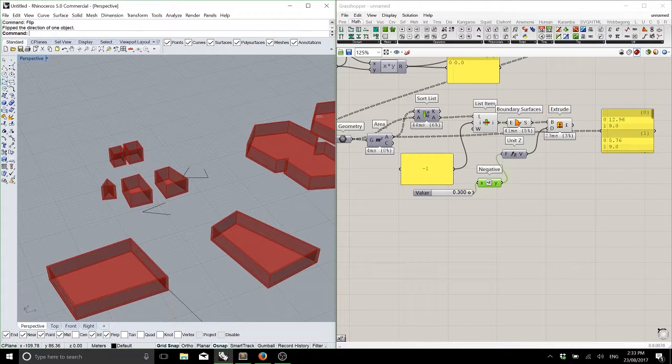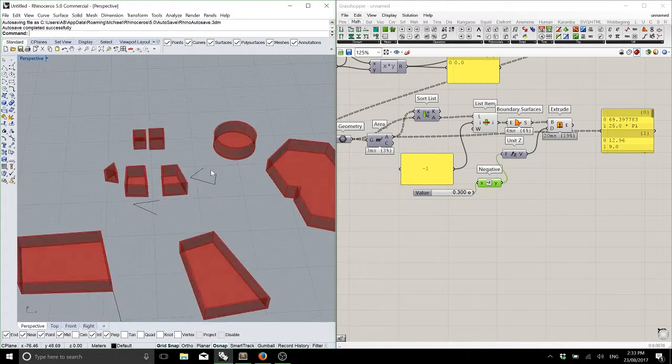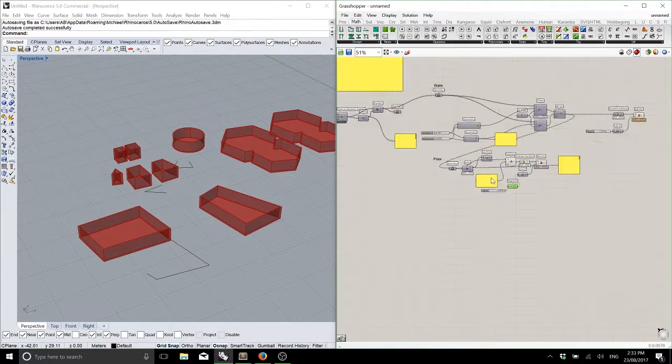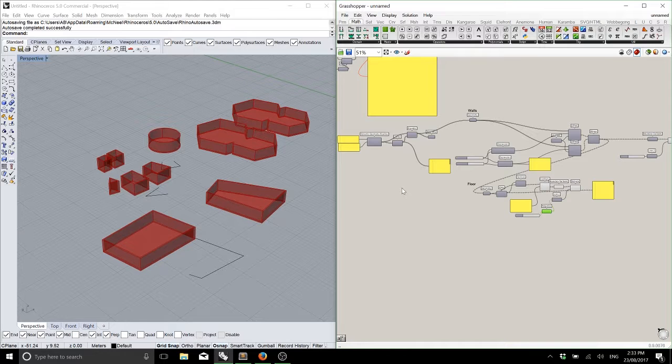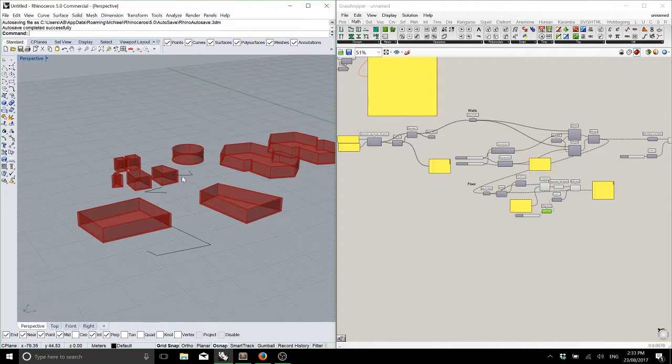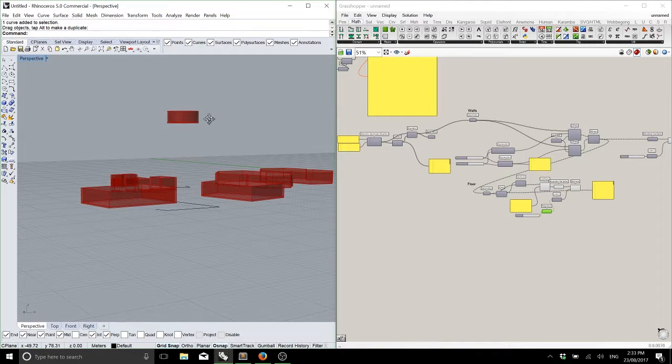So yet again, just to hammer that nail in, I draw a closed curve, I get walls, I get a slab. Do you understand how every time I add this curve into the system, I am not copying and pasting this script? The script is designed to work with any number of rooms. If I grab a room and I move it up, the system works with it.